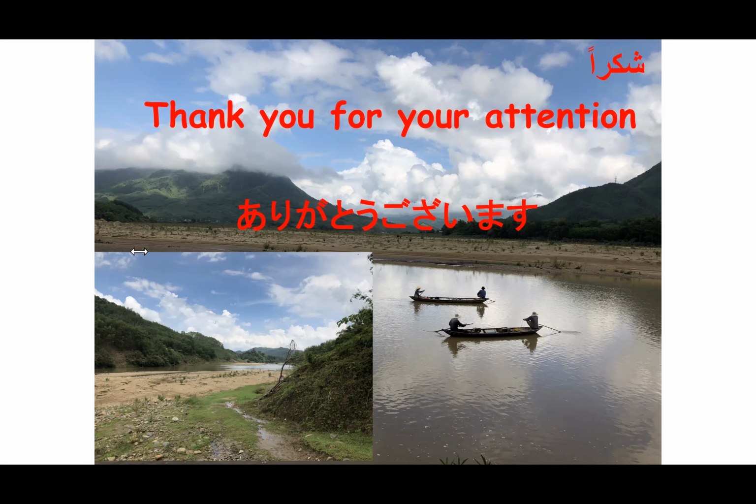You will increase the dam height, but you cannot recover the reservoir for the full storage because of the dam safety issue. So considering the sediment management option from the beginning will reduce the cost, as we saw in many cases in Japan and worldwide. Thank you very much, Professor.